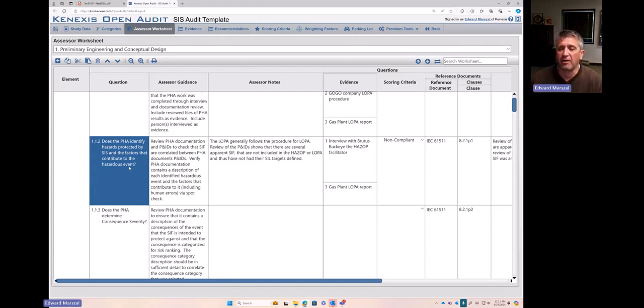If we're talking about a medium-sized SIS project, let's say 20, 30 safety instrumented functions, stage 3, which means I'm going to do stage 1, stage 2, and stage 3, is probably going to take, let's say, about a day of base load time, maybe a couple days of team time and review time. So maybe 3 days of effort there.